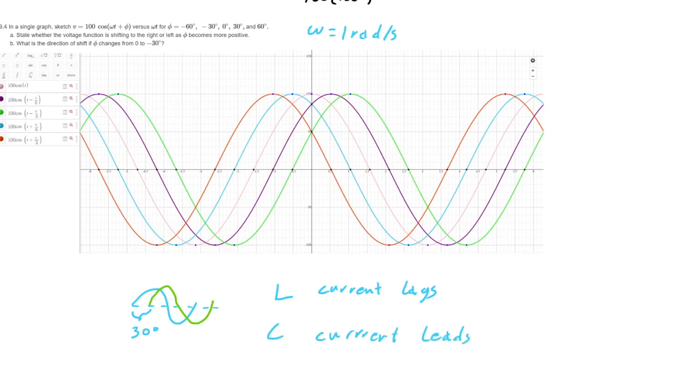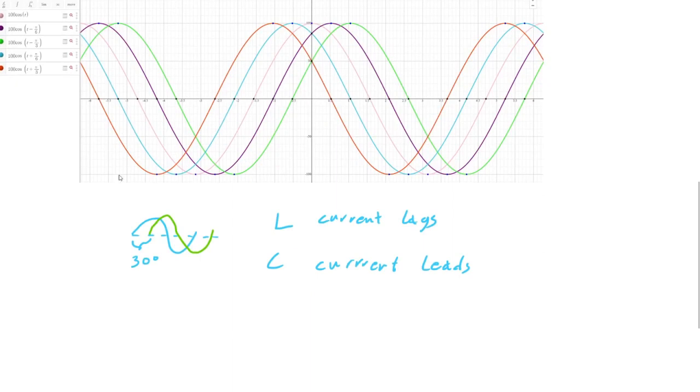And you can see that if you think about your equations for the components. Remember, i_C(t) is C dv_C(t)/dt. Looking at that equation, it makes sense that the current is going to change more quickly than the voltage. In fact, if you integrate this, you'll see that it does.